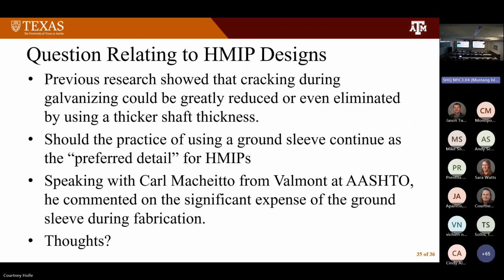I remember Rob Connor at Purdue looks at the ability of inspectors to find certain defects, and you'd find that bad ones sometimes found things that the good ones had, but then some of them couldn't find anything. It's the probability of detection, right? You need to make sure that if these defects are there, your inspectors can actually find them, because it doesn't jump out at you. You can't say, oh, there's the crack right there. So we're hoping to provide something so the inspectors have confidence that they can actually find these cracks.